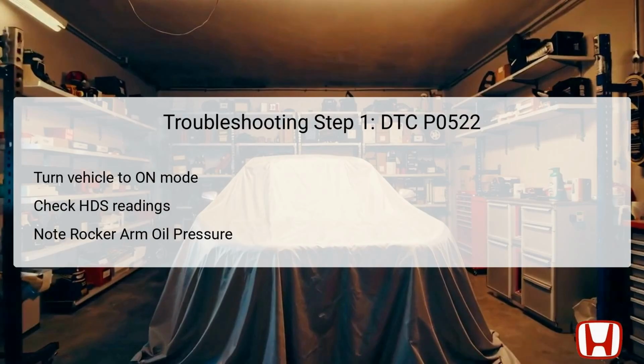If the readings show values less than 0.18 volts, it confirms that a failure has been duplicated, indicating a problem with the sensor or its associated circuitry. Proper usage of the HDS tool ensures that the technician can gather accurate data to inform further diagnostics. This step is vital for establishing a baseline of the sensor's operational status before proceeding with more intrusive inspections.